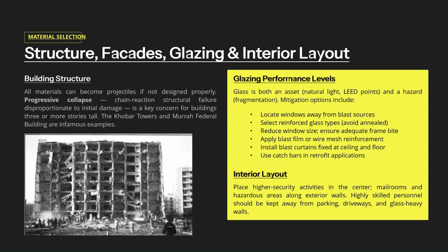Glazing, or the use of glass in buildings, presents another important consideration. Glass can act as both a functional and aesthetic feature, but it is also a potential hazard during explosions or forced entry attempts. Laminated glass, window films, and controlled placement can significantly reduce risks from fragmentation.